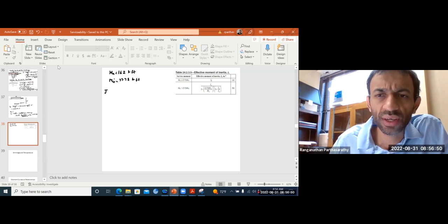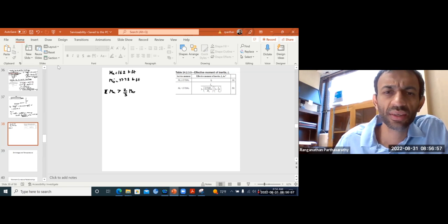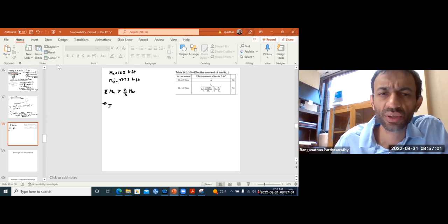So what's your I? Your MA is obviously greater than 2/3 of MCR, which means your I is I effective.